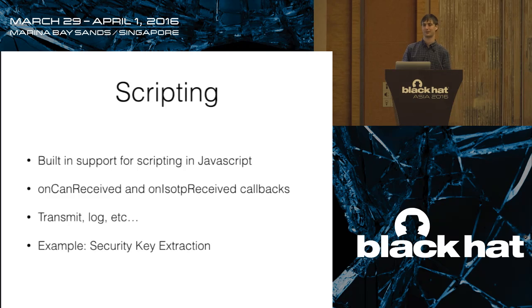I could probably dump the firmware from that, do some disassembly of it, and figure out where they're storing these keys. That's one option. But a lot of the time these security access mechanisms are not very secure. So I wrote a simple script that pretended to be a car. Whenever it received a request to send a seed, it would start at 0 and send the next consecutive value. So you get the seed of 0, 1, 2, 3, 4, 5, 6, 7, and keep going, and whenever you got a response, it would print out what the valid key value is.